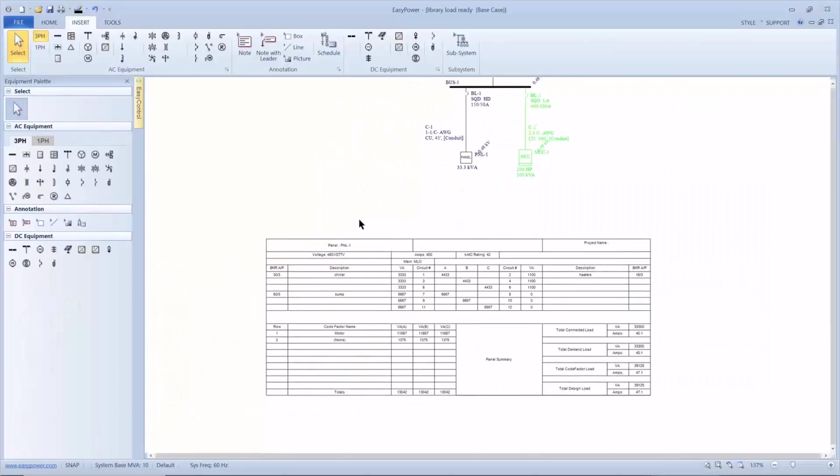Right now, I've already established the schedule. I've already populated both the MCC and the panel. If I were to change the pointer to the ArcFlash icon, which I have in my device library, it wouldn't change the existing schedules. But any new schedule that I build would change.